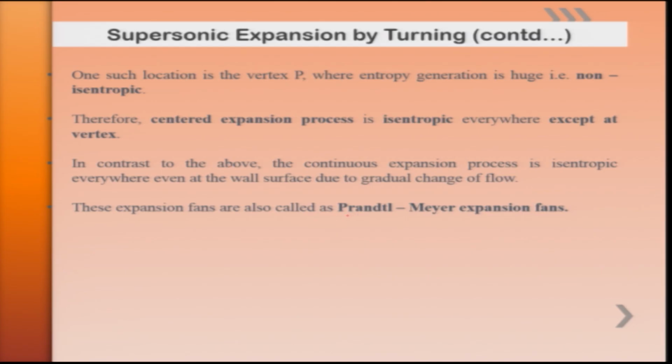Please note it down that these expansion fans are commonly termed as Prandtl-Meyer expansion fans. Now, likewise the shock waves which we have deduced, like oblique shock waves, relationship, static property ratios, density ratio, pressure ratio, temperature ratio, stagnation pressure ratio. Likewise, how to calculate the downstream properties when the upstream supersonic flow is meeting with these expansion fans